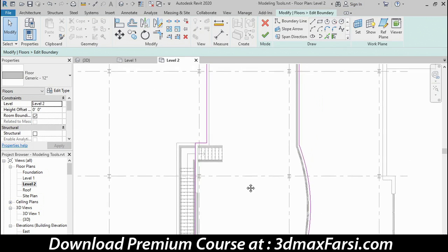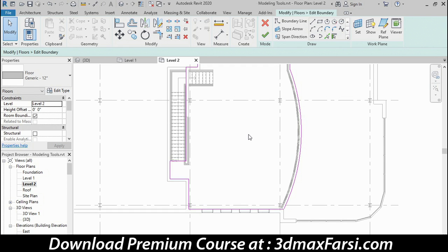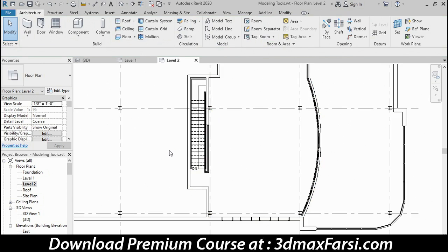The difference is none of these have that little triangle on them, which indicates that this is a completely flat floor element. So if you have none of the edges with slope assigned, it will be flat. And if you turn on that slope defining edge, then it starts to slope it. But otherwise, floors and roofs are very similar to one another. I'm going to click this red X to cancel out of there without making any changes.